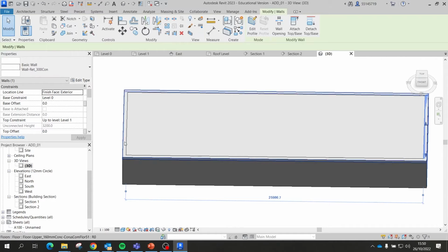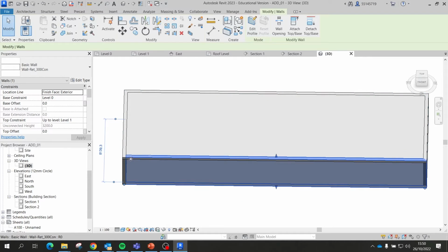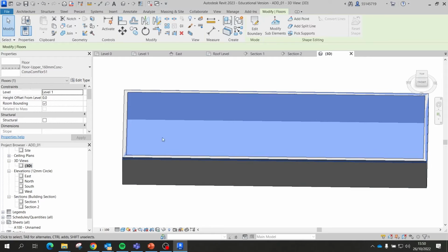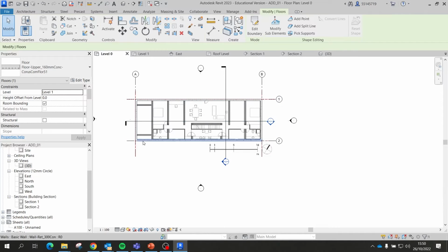How do I do that? I can select the walls. Do they have walls in place? Just one. So instead, we did a rectangle instead of using a line for the wall. I switched to rectangle because it wouldn't make sense. We have all the perimeter walls. It's just a rectangle. So just use a rectangle tool, and then, if you're on level 0, just use the grid as a guideline to create the rectangle. And I will create rectangular walls.